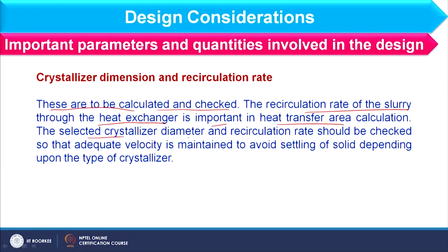Further, the selected crystallizer diameter and recirculation rate should be checked so that adequate velocity is maintained to avoid settling of solid, depending upon the type of crystallizer. So, all these points we should consider in the design of crystallizer. So, let us focus on the design of crystallizer.